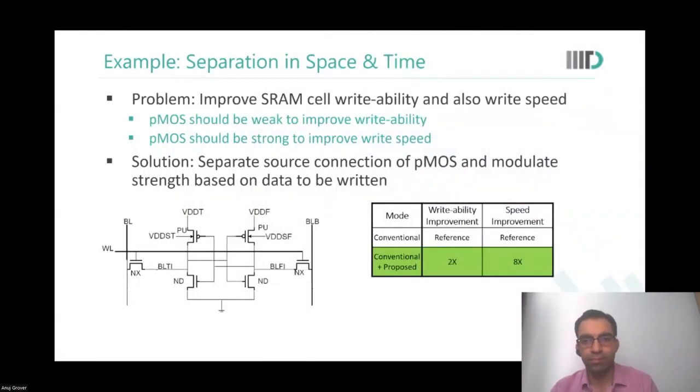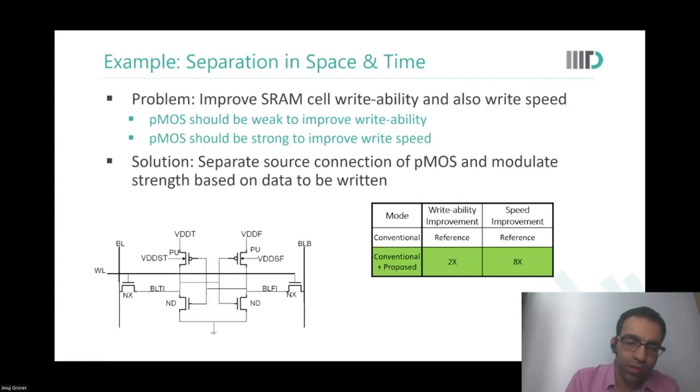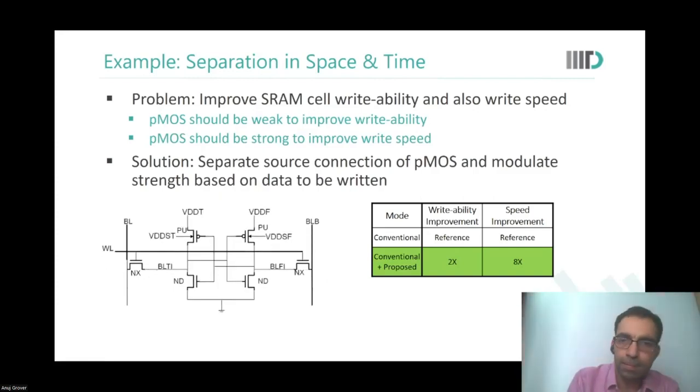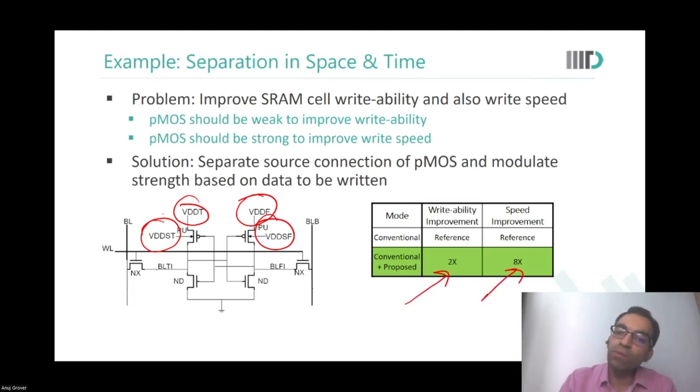Yes. So we said that we have actually split the supply voltage, segmented the supply voltage, given different body bias voltages also, and we could say that the solution not only improved writability, it also improved speed. And this was at almost zero cost, because splitting this, we had area there. We did not have to put in any additional area. We just had to put an additional wire there.